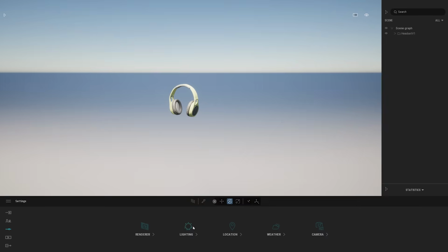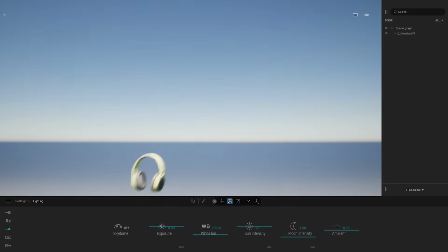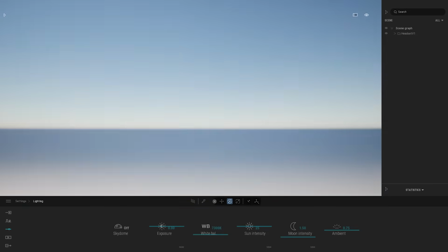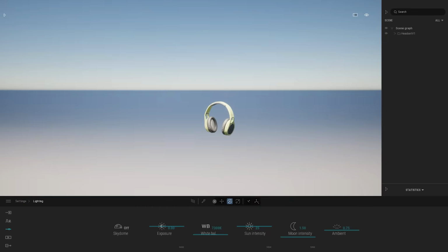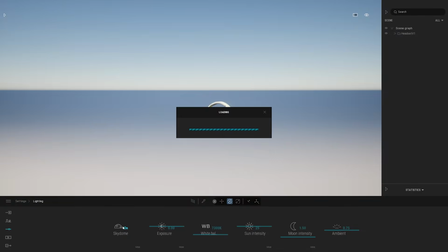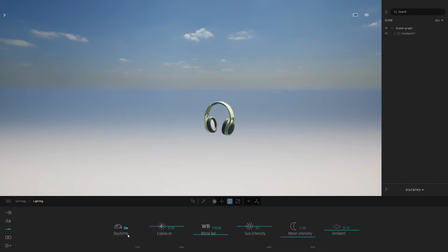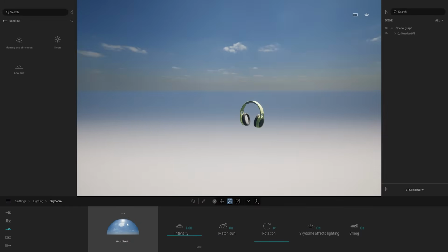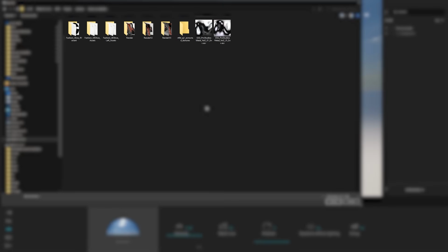The next step will be in the lighting. Right now we have that default sky. Here in our case, I want to load a studio type of HDRI. So this is done with the sky dome option. So I will click on, turn it on. It will by default enable an HDRI of a sky with some clouds. And I can go to the more and load my own texture. Today, what I'm going to use for this webinar is an HDRI coming from Grayscale Gorilla.